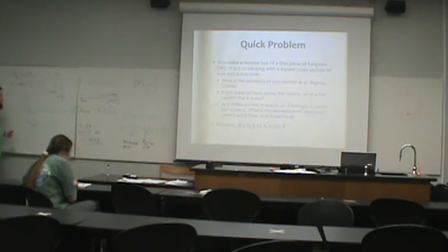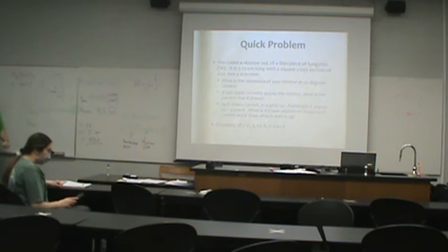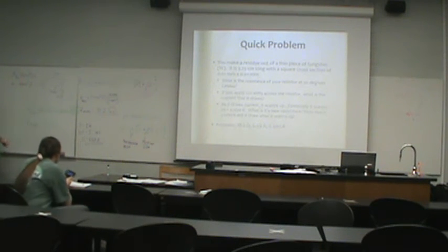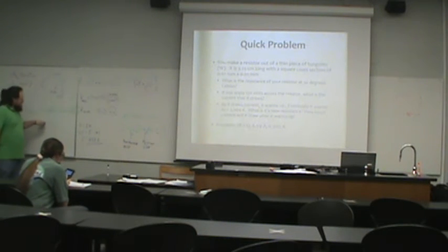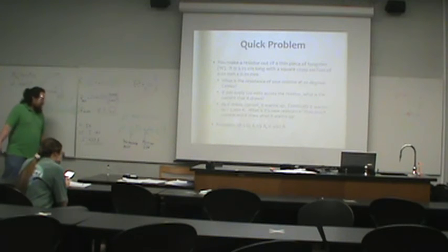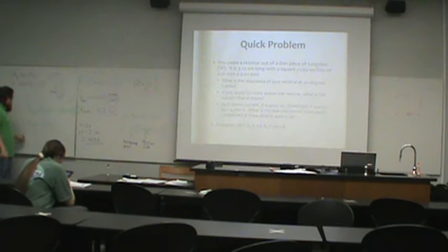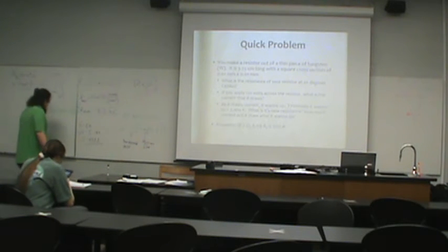Because what's going to happen to the current inside the machine when this happens? We perform the same operation. We're just going to take our new higher resistance and plug it in instead of 18.2. So what does that make the current at 3,000 Kelvin? 0.5 amps. Actually, the answer was up there, I'm sorry. It's not a spoiler. So that current dropped by about a factor of 12.